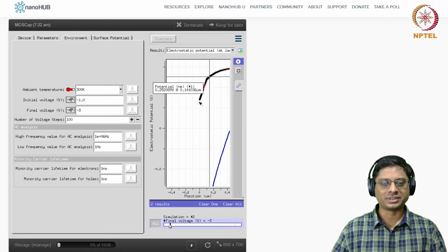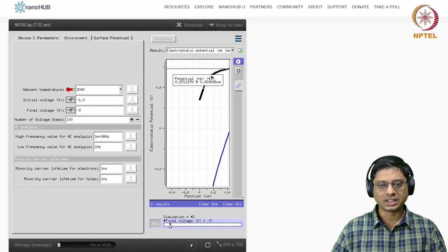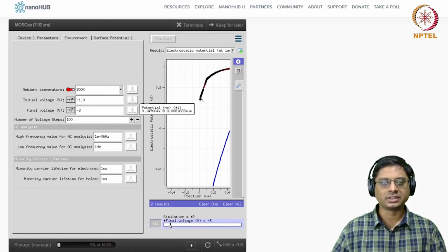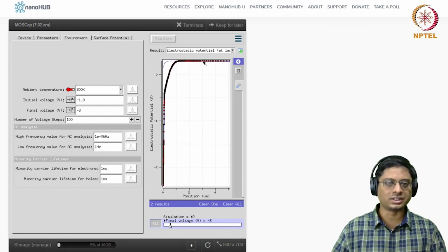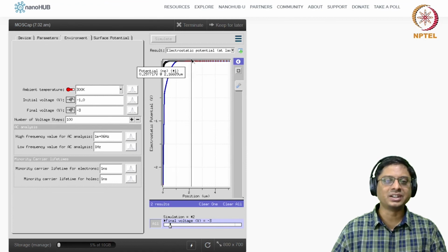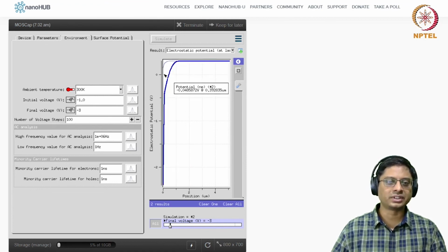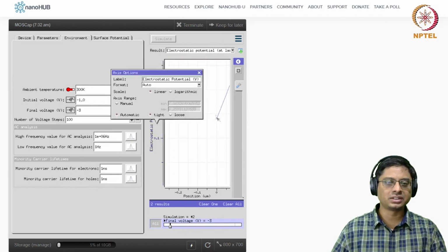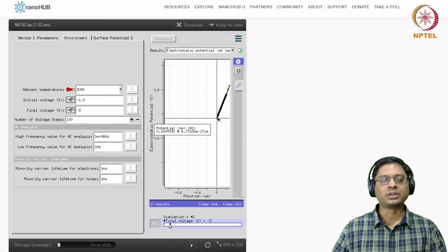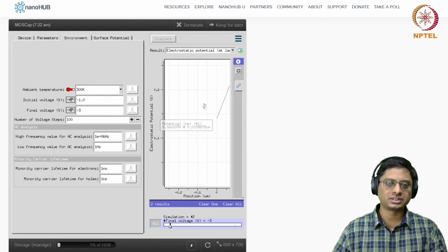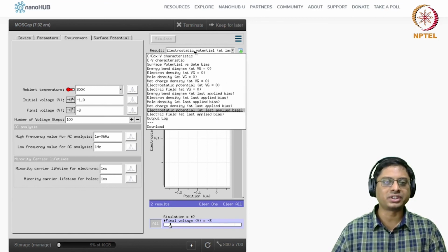Well, we are not reaching it also. There's a gate voltage that should be linear here. So till here it is quadratic, and then it is linear. So this is how the voltage will be. This is an applied voltage of about, if I take this to be 0. Oh, okay. The simulator takes the reference slightly differently, 0.3 as a reference. So with respect to that, we have 0.14. So there is this gate potential, electrostatic potential, that you will see.